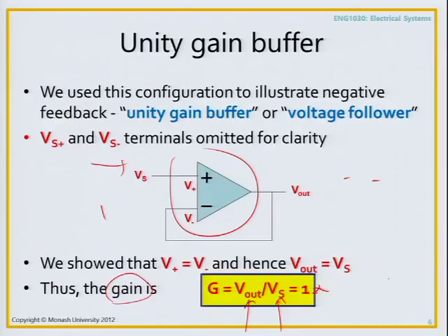So over here, you may have signals which are really tiny signals. They may come from sensors such as you might have a photosensor which detects light, and they produce really small amounts of current. But I want to be able to amplify that signal, but I can't draw lots of current from that particular sensor. So what the op amp does is it takes that signal and gives you a whole lot of current out so that you can work with that.